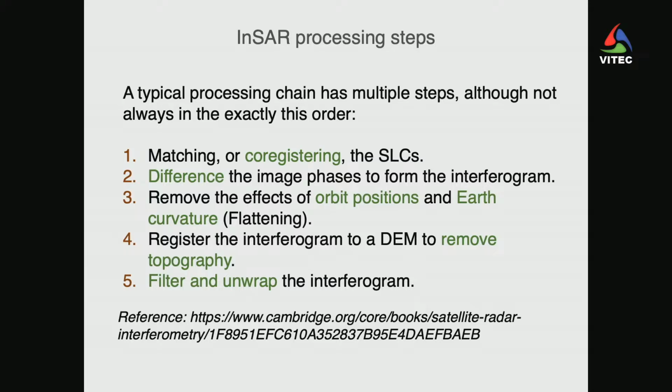The very first one is what we call the co-registration of the SLCs. SLC is a format we're going to go through in the workshop session. It's a common radar format that probably no one else outside the radar community knows. Co-registration means getting all these images aligned with each other, so pixel 1 in image 1 means pixel 1 in image 2, at the same ground location. The second step is to calculate the phase difference, and that's the actual critical step to form the interferogram.